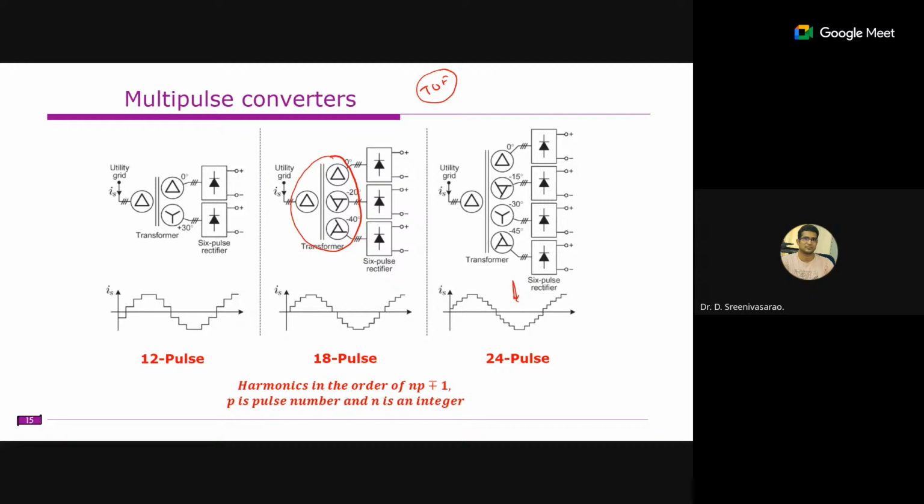Another thing is that these transformers will take up to 50% or more of the space, weight, and cost as well. That's why this is normally used in HVDC and FACTS applications. By using this, we can directly go up to 220 kV or even higher. You can integrate to it. Nowadays, even HVDC is no longer using this. By using modular multilevel converters, we can overcome this problem of using transformers.